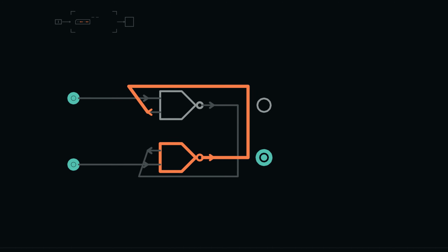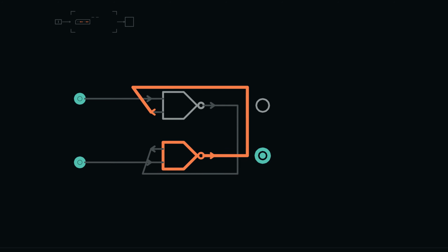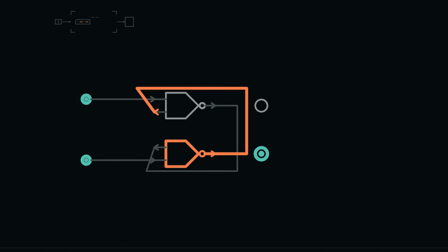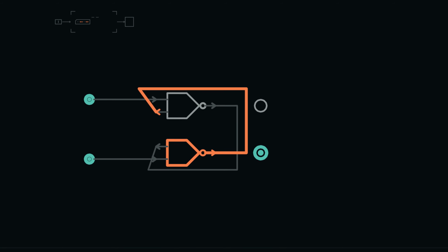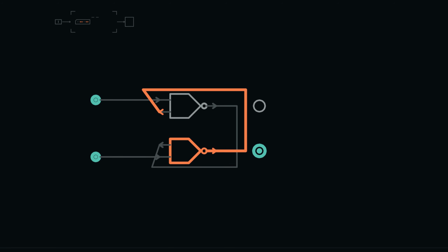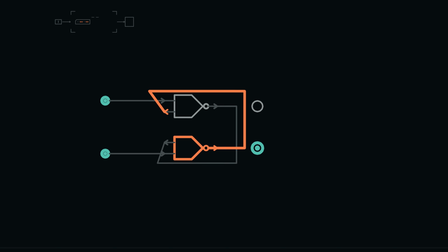These external controls are active-low, shown by bars over their labels. 0 performs the named action and 1 leaves it inactive. This is an electrical convention, not a new kind of bit. A 0 on the set input requests set, a 0 on the reset input requests reset. When both are 1, neither action is requested. Saying this first prevents the common error that one must always mean do something.